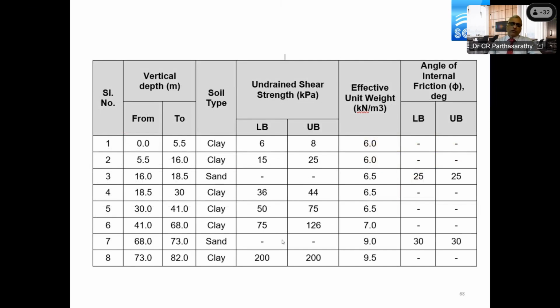So it's tempting for us to ignore the sand layer if you are making an assessment for foundation, maybe pile foundation, where it's not very relevant. But in this case, the legs will penetrate this weak material and temporarily rest on top of the sand layer, but the sand layer is very thin and the material below the sand layer is also weak, and therefore it becomes a strong over weak condition.